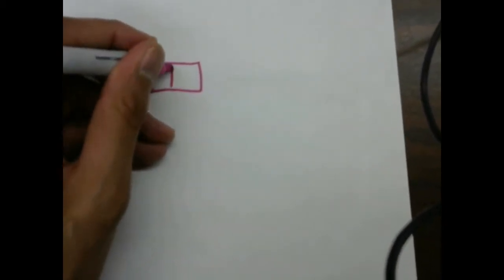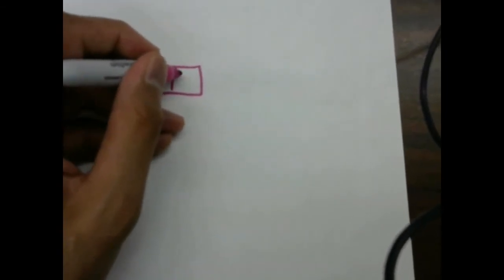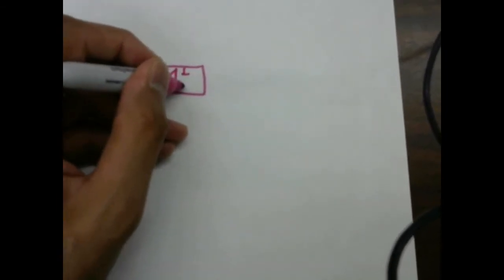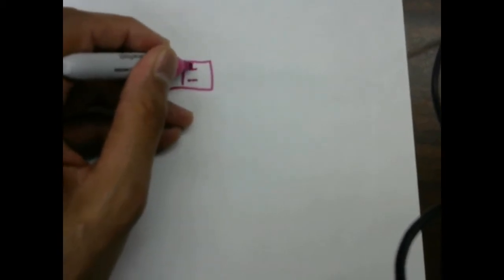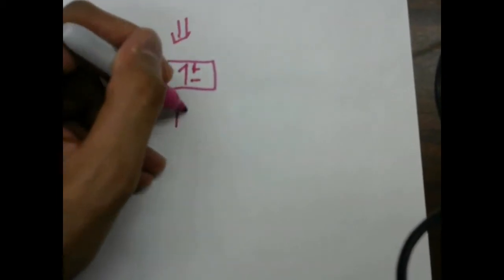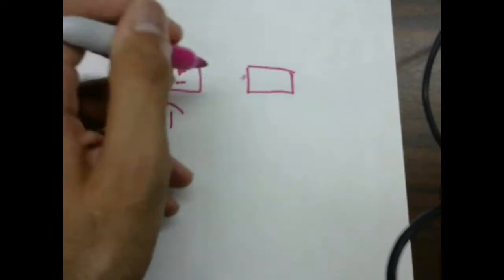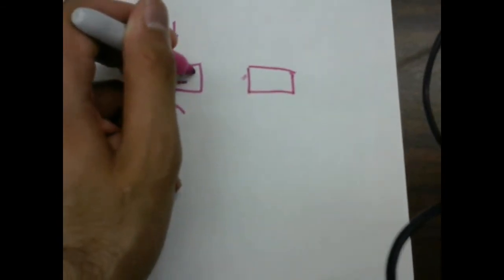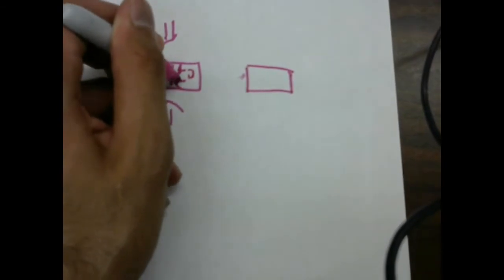Now if we continue to describe that, when we have a piezoelectric material and it has a certain polarization, remember the polarizations end on positive charges, and the tail is negative. It's opposite to the electric field. If we push on it, these positive charges will be going down, and these negative charges will be going up.